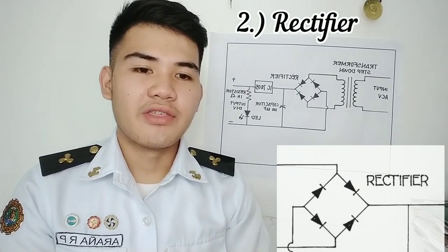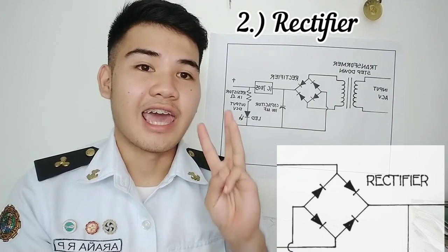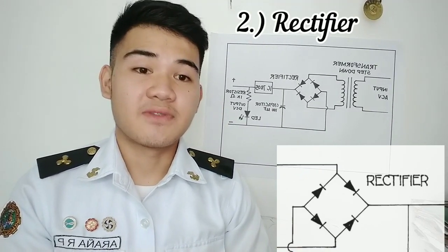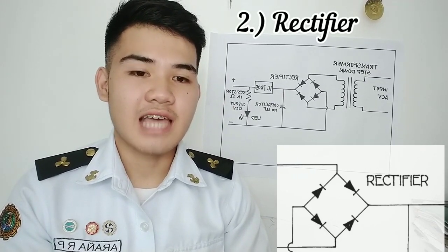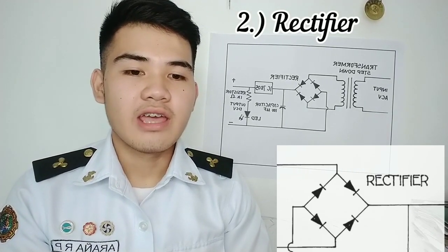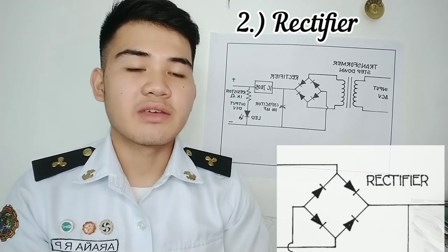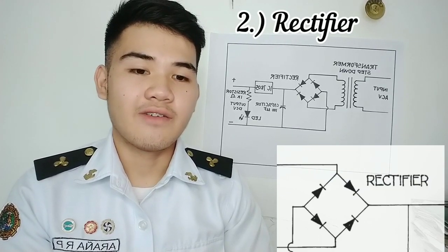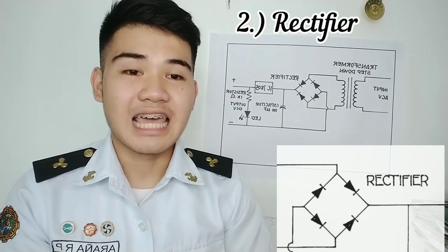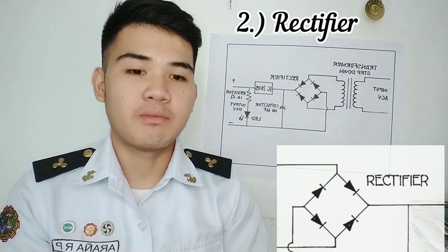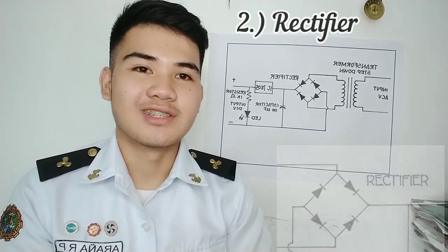The operation. There are 3 major components of the rectifier: the transformer, the stack, and the cabinet. The purpose of the transformer is to safely separate the incoming AC voltage from the secondary side. The stack is the actual rectifier and is comprised of a set of silicon diodes or selenium plates that function as unidirectional current valves. Next is the cabinet. The cabinet, which includes the test panel, safely houses the components and allows for monitoring and other advanced operations.